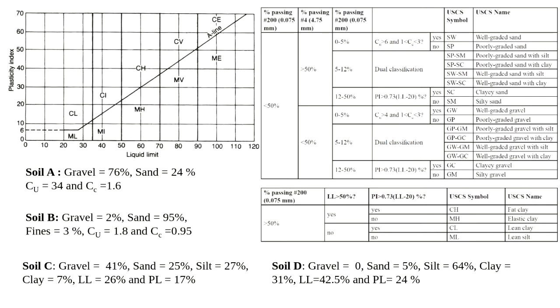What I'm going to do is I got these numbers, like gravel and sand, based on the boundary of 2.36 millimeters. So this is okay when we use the AASHTO soil classification system, but we have to recalculate these numbers. So I'm not going to do it. I'll just assume that they're still the same. But you shouldn't do that when you work on your project, because I don't have time to do that, and you probably already know how to do it.